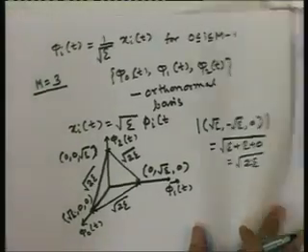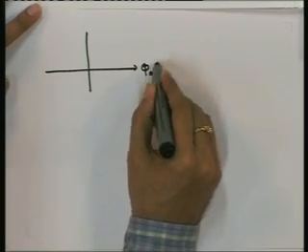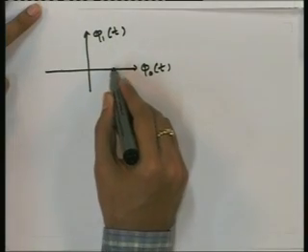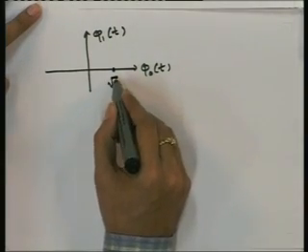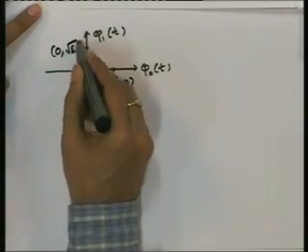Okay. Similarly, for the two-dimensional case, it will have only 2 dimensions, for m equal to 2. And remember here that the dimension of the signal space is same as the number of points, 3 here. So for the two-dimensional case, this is phi_0(t), this is phi_1(t), and here is one signal point, that is (root E, 0), and this is another signal point (0, root E).